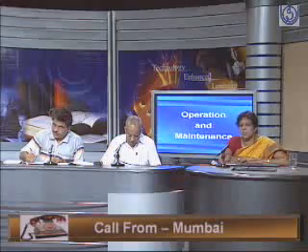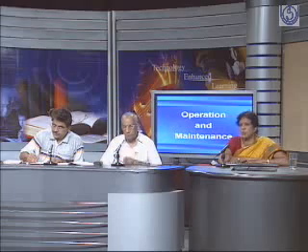Okay. Well, first we'll answer the question and then we'll move on to reactive compensation. The faults in a distribution system generally occur on the LT side. Most of the faults are observed on the LT side. Generally the HV coil doesn't fail much. The LT coil fails, and 65% of the faults on a distribution transformer occur on the LT side.